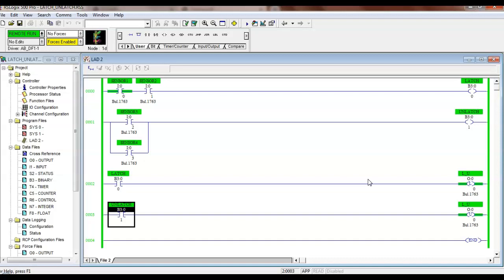So think, and that's what PLCs save. They save those internal cores. That's where it saves those relays. So when we look at a cabinet, we showed y'all it's got 500 relays in there. And then I show you it's got 4 relays that turn on motors, and all those other relays are gone. Well, all those other relays, those are what we call control relays. They're not in the circuit to turn on a motor. They're just in there to make decisions. Does that make sense?